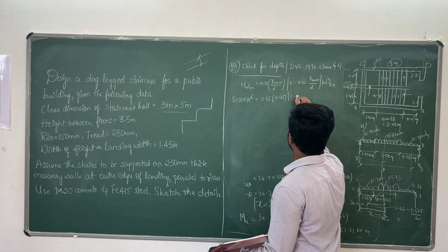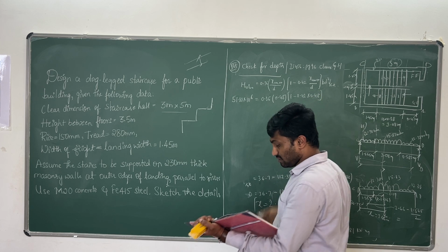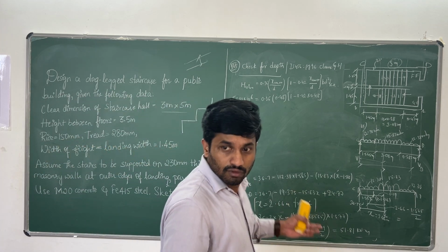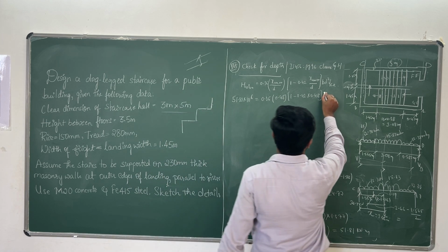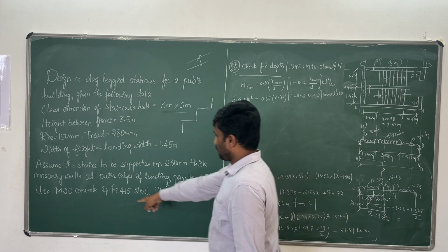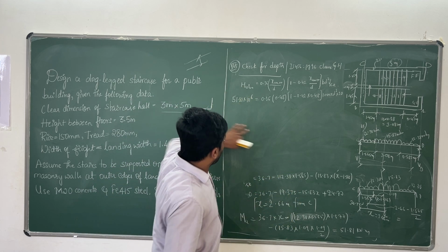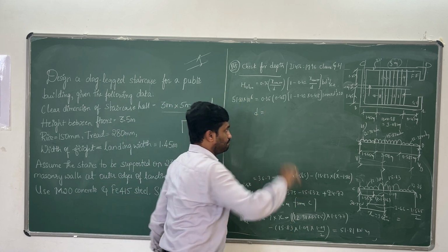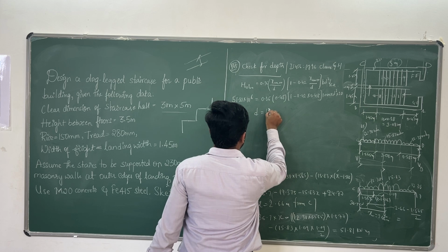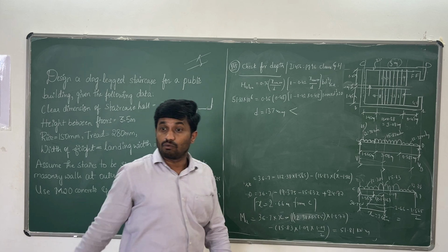So 1 minus 0.42 multiplied by 0.48, B, breadth 1 meter. Depth always we will do for meter. 1 meter, which means 1000, into d square, grade of concrete is 20, given as M20. So d, we have to compute d. Now solve all this, check what is the d value. How much are you getting for d value? Please check. 137.0. Okay, 137.